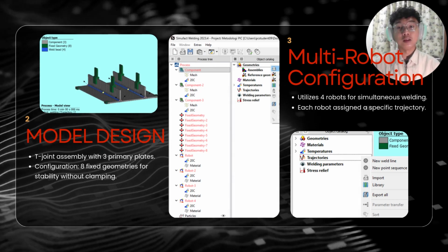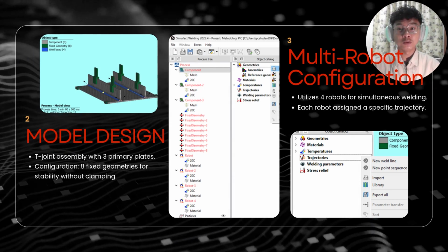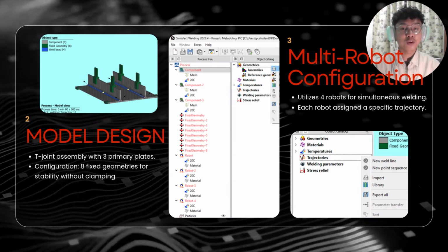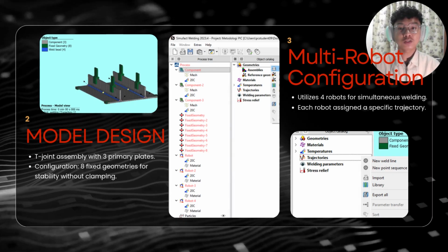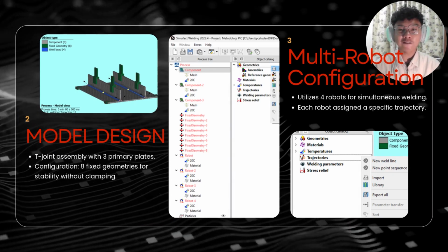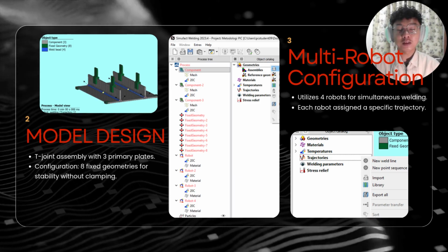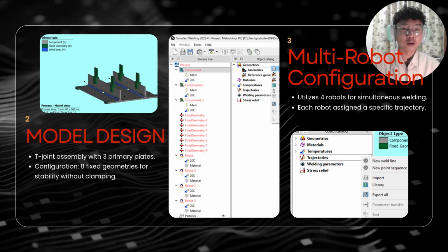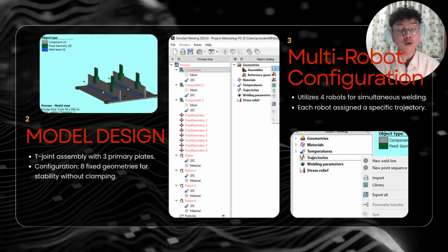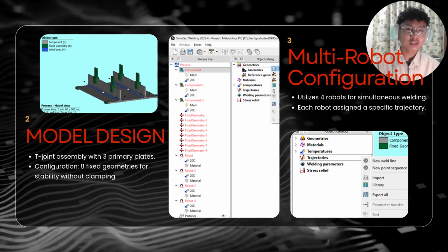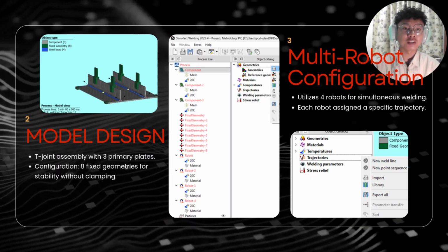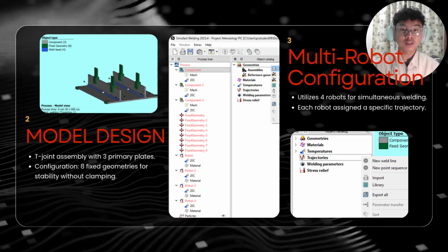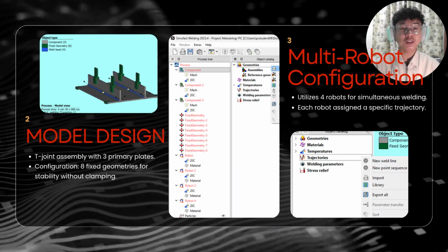Moving on, the model design for our project uses a T-joint assembly with three primary plates, which also has a configuration of 8 fixed geometries for stability without the use of any clamping. Next, our project uses a multi-robot configuration which utilizes 4 robots for simultaneous welding. Each robot is assigned a specific trajectory.